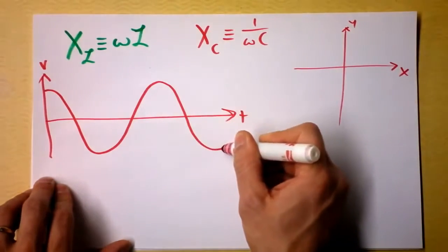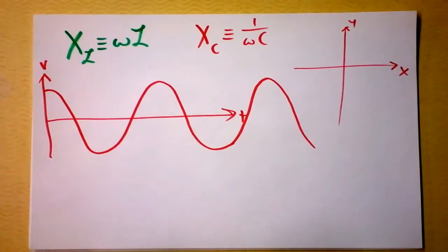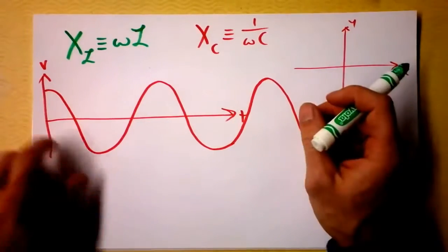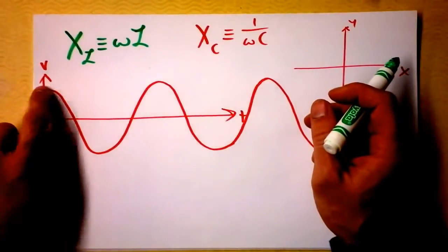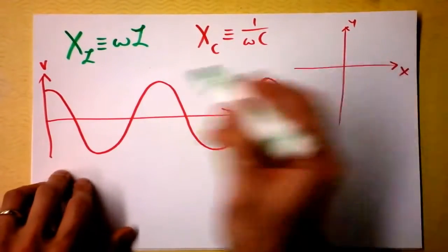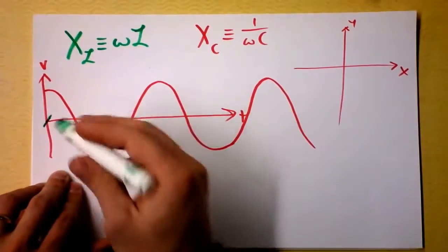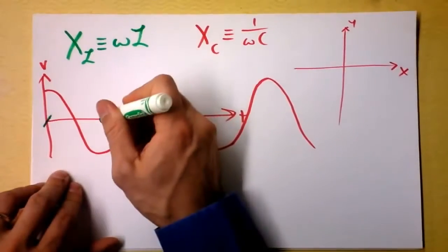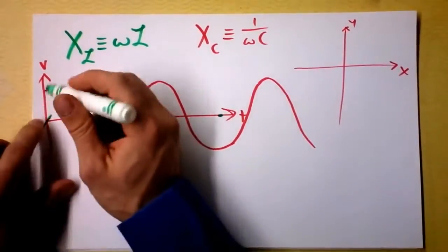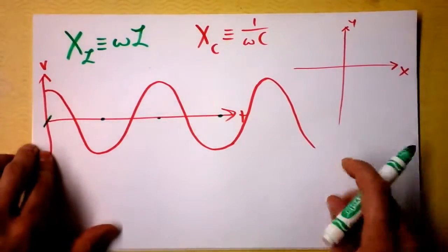And this is my power supply. My power supply is just doing the best it can. It's trying to make the flux change through an inductor, and the inductor's entire reason for being is not to let the flux change. So you know that the voltage is the derivative of the change in flux. So the current is going to be 0, but maximally changing here. And it'll be 0 here, but maximally changing, and here, and here. And so initially, there is no current. If the voltage is very high, there's no current, but the current begins to ramp up.